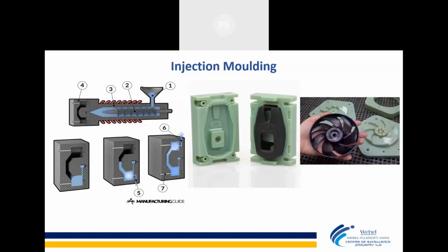pushed. Like if you can see this, this is the raw plastic, in raw block form. Pebble form, granule form plastic has been put. The plastic goes inside the hopper. A very high temperature is applied, where the plastic is melted, completely into liquid form. Then there are plungers, you can see these kind of round things, plungers. They push the material forward at a certain pressure.